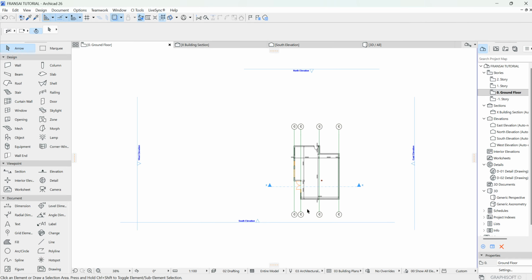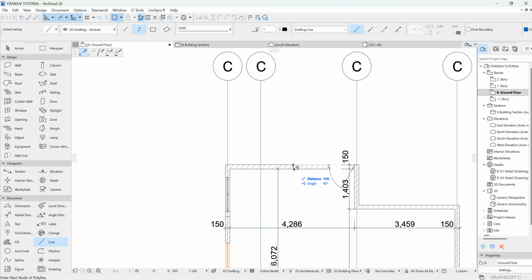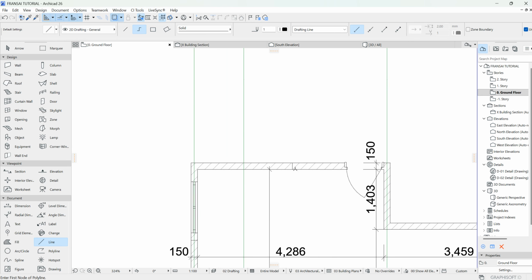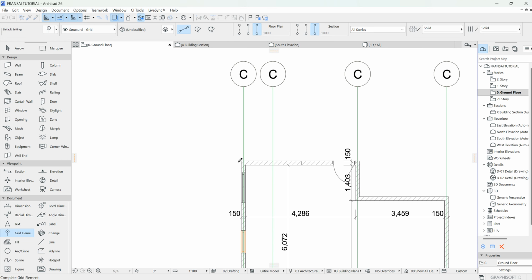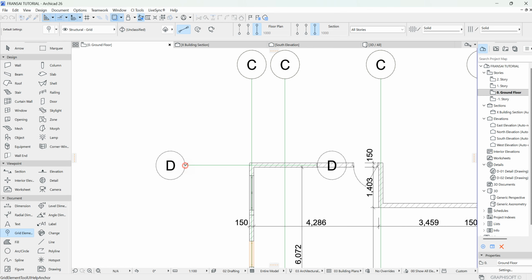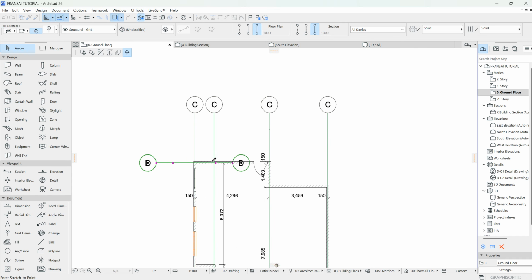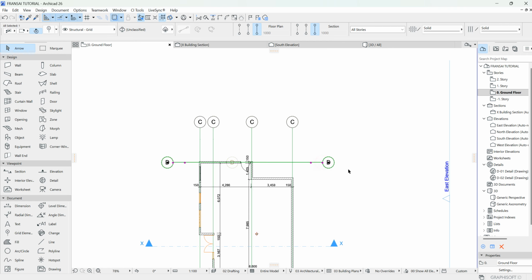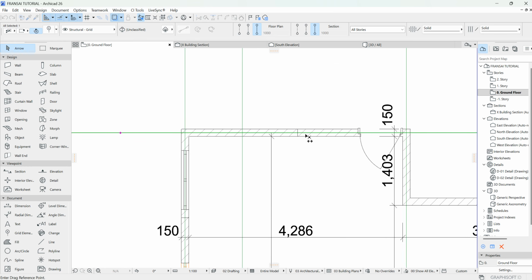Let me show you the setting I usually do on my grid line so that it doesn't actually interfere with the floor plan. Or let's place the other one on the horizontal lines before we do that. Okay, I draw this line. So click on the grid line. I can equally click it here on that center line. Click it there. Place this there. Then I can just drag this out. So I will just duplicate it, drag multiple copy.